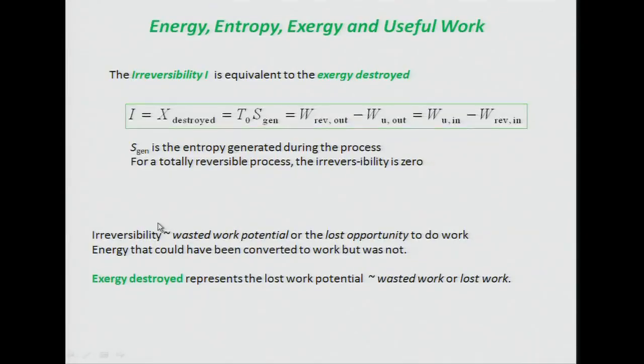And so we can think about the irreversibility in the system now in terms of wasted work potential, all right, or lost opportunity to do work. Once we've destroyed that exergy, we can't ever have it back. And so we're really wasting a resource there. Unlike when we talked about energy, because of course you can't destroy energy, but you can destroy useful energy in a sense, which is what we're talking about with exergy.